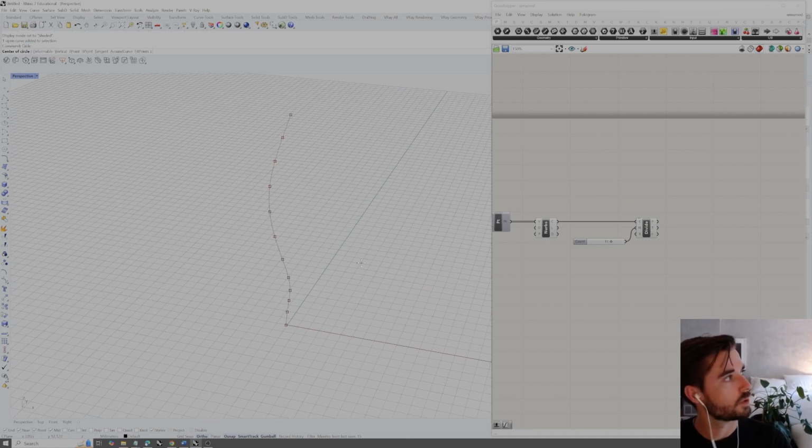So if I drew a circle in Rhino, and I wanted this circle to move from where I've drawn it, from its current location, its base location, to my curve, so that I could loft through these profiles on the curve, what I would do is type copy, and I could copy from the centroid, so object snap centroid on or center on, to each of these points.